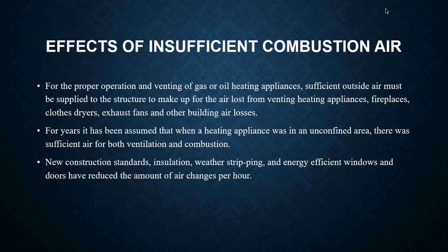So for years, it's been assumed that when a heating appliance was in an unconfined space, and we talked about an unconfined space in a previous lesson, there was sufficient air for both ventilation and combustion. That's really not the case anymore, especially with newer construction.